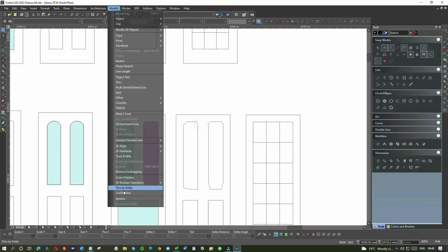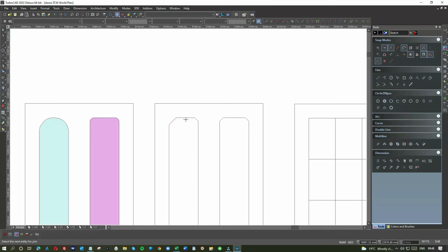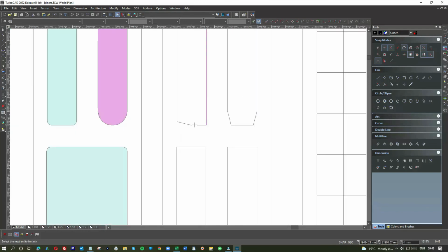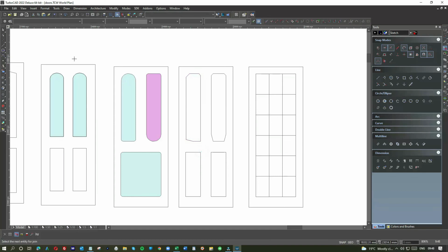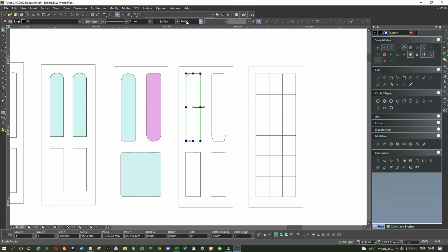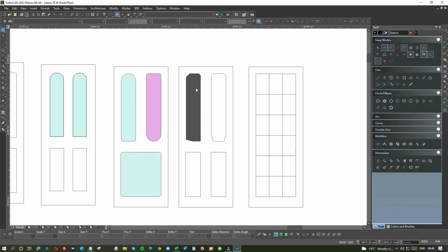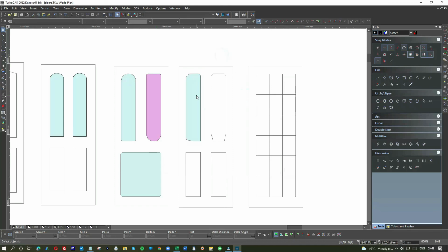You click and you're getting one entity, so you're going to have to join again. To do that, we go to join by polyline, and let's go around, join these elements. That's it, and then right click, finish. Now you have effectively a polygon, so you can actually fill it. Okay, so if we change the color and we go back to blue, here we go.